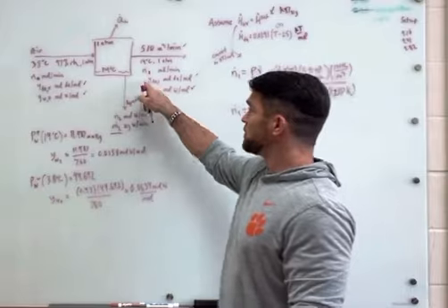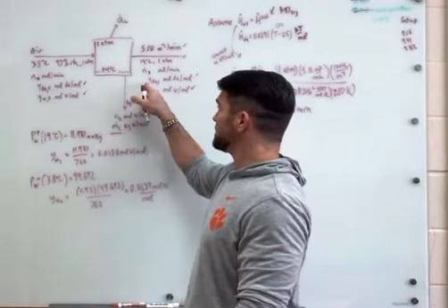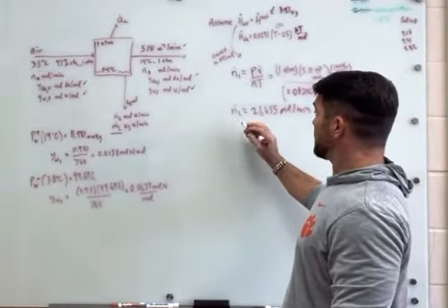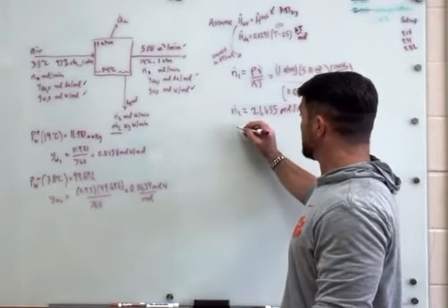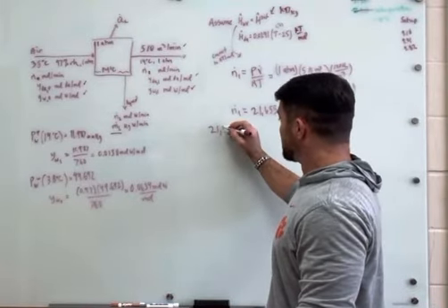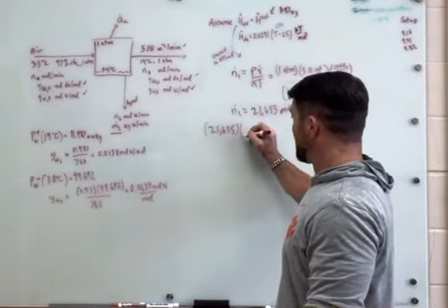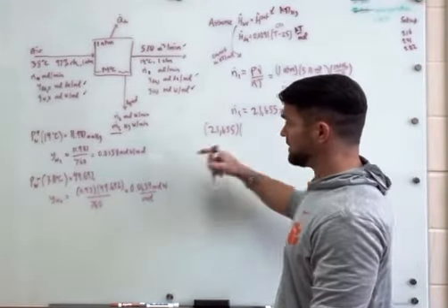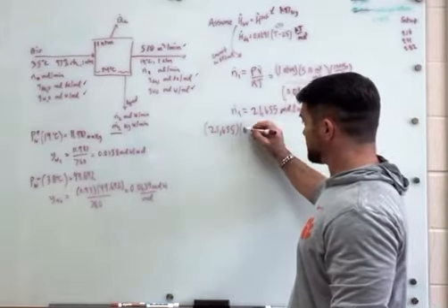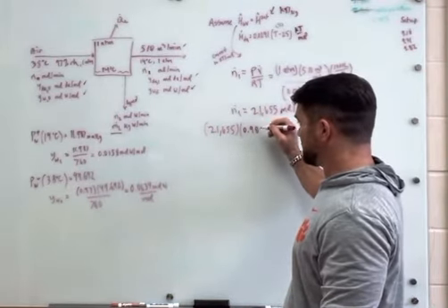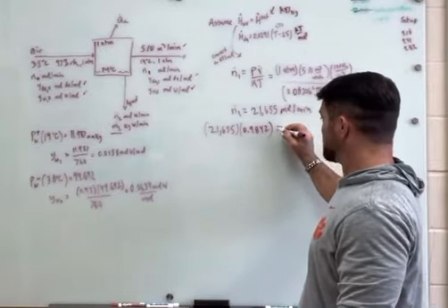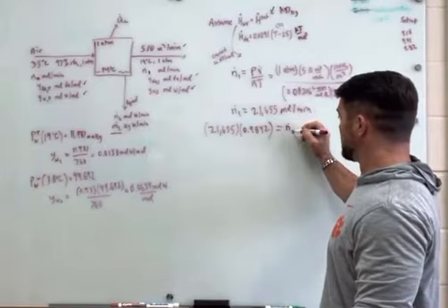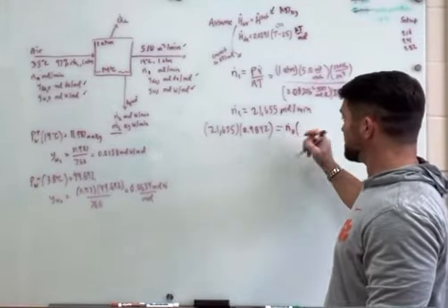So the total number of moles of air in this stream equals the moles of air in this stream. From this balance, the moles coming out are 21655 times the mole fraction of air in this stream, which is 0.9842. And therefore this equals the total mole rate in this stream times the mole fraction.